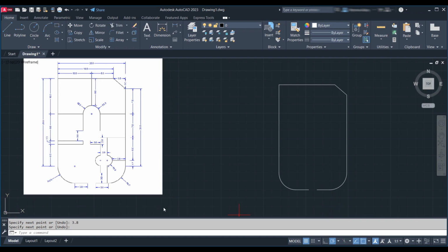Guys, as you can see, it is very easy to draw plans if you use the drawing aids. Now interior lines. This line I don't know the length of it, but I know the length here and the distances, so I can easily draw this line. Activate the line tool, L enter. I wanna draw a vertical line from this point that is 10 meters away from the start point. Move the cursor to the start point and then slightly to the right. Type 10, enter.